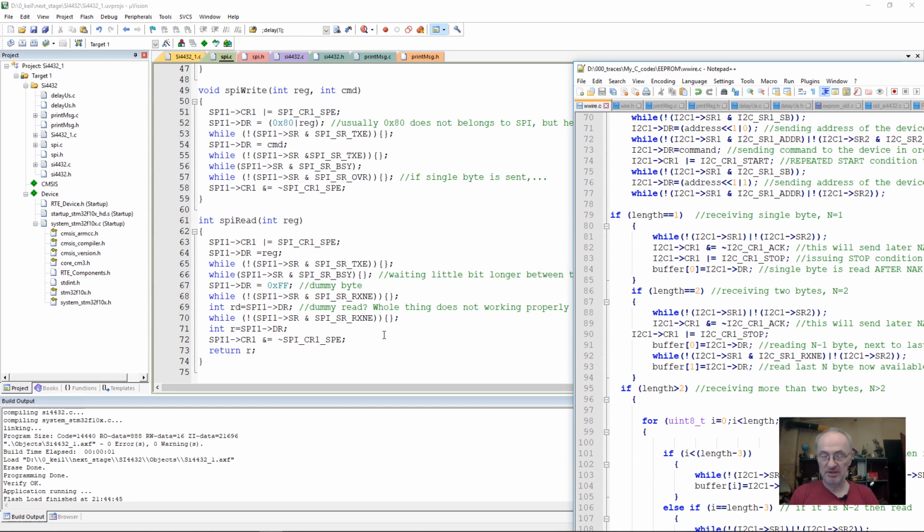I'm happy to get this module working, this transceiver. It bothered me for many years. I got it semi-working, but not good. So I rushed sending byte by byte: pulling down the NSS wire, sending 1 byte, pulling up, down, up, every byte. Instead, it is actually better to pull down once and send the whole 64 bytes at once, saving time.